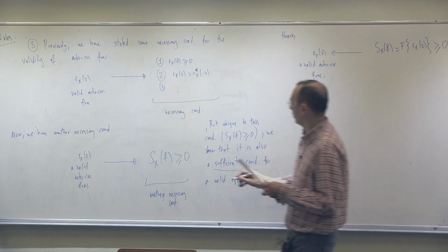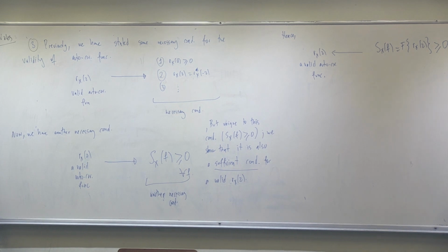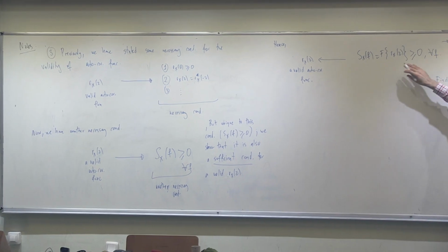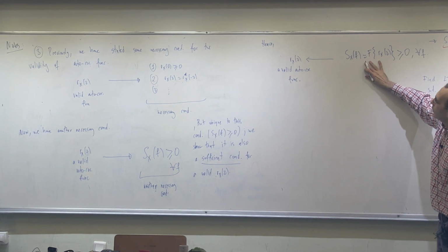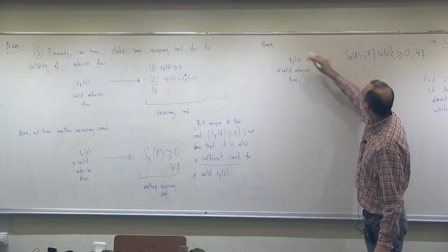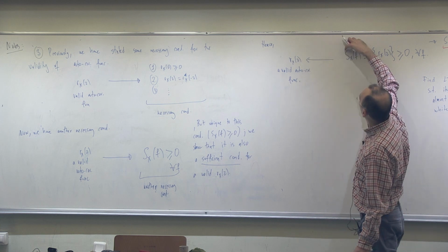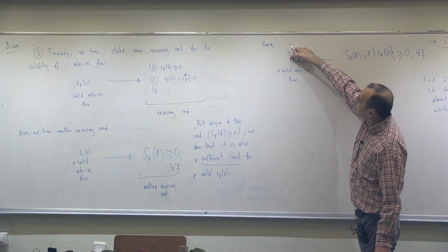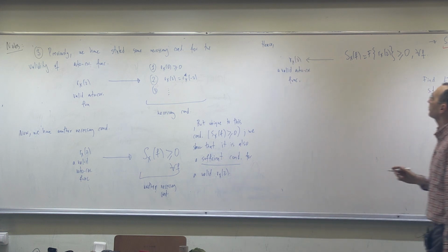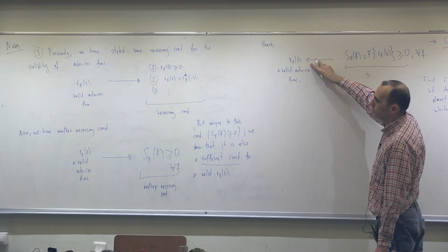Now, first of all, this should be satisfied. If this is satisfied, I am sure that the inverse Fourier transform of this claimed power spectral density, Rx of tau, is indeed an autocorrelation function. So this is the sufficient condition. The arrow is reversed, as you see.